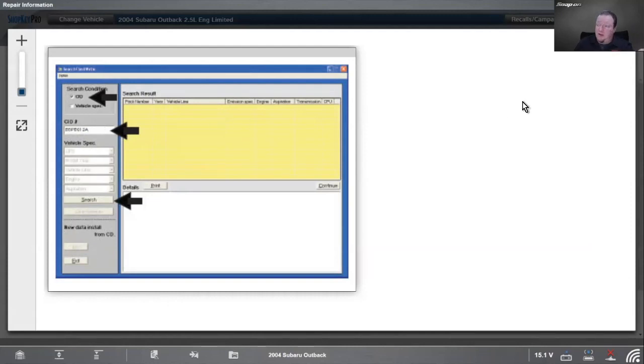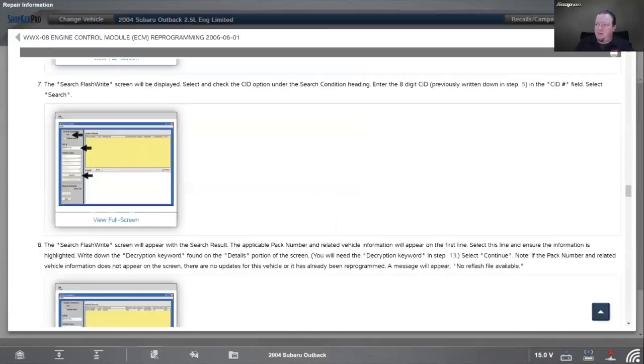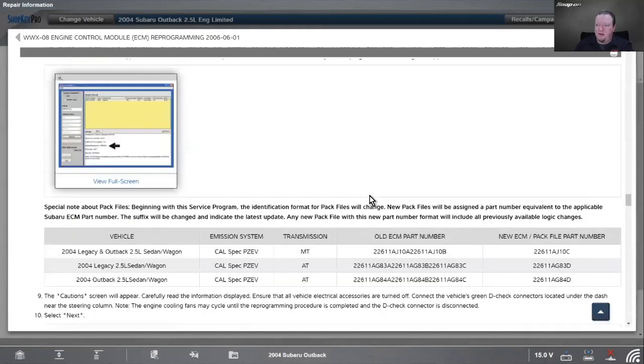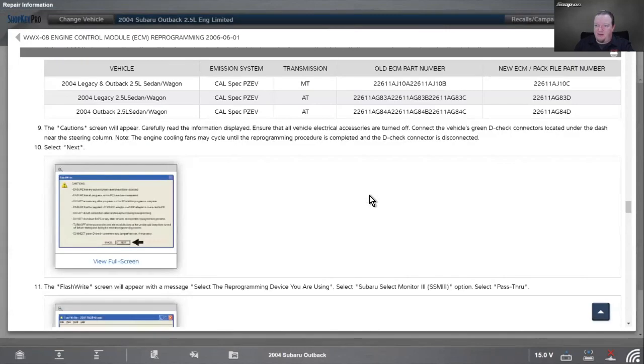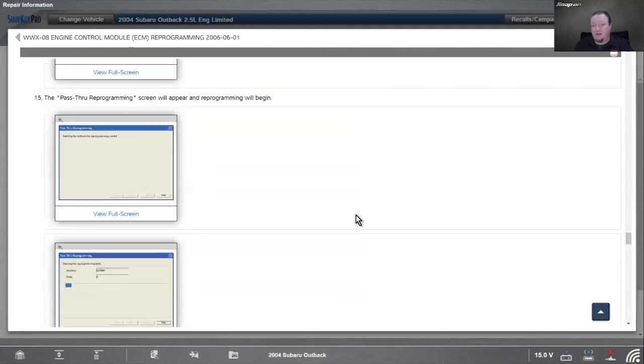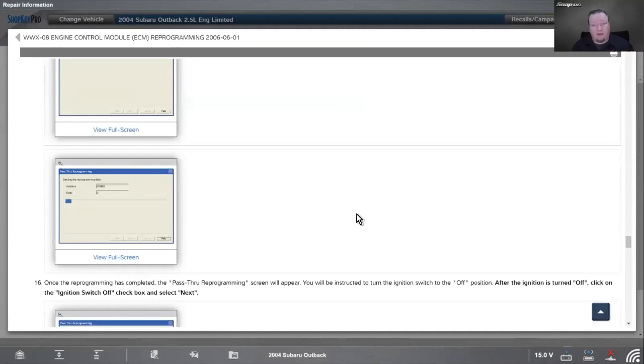So that was just one reason we use that. They went from that to computer part numbers now, but you can still check the cal IDs. Sometimes there were different TSPs you would need to use to check whether or not it was applicable to that vehicle. So that's how you would know when it's on the latest software version.